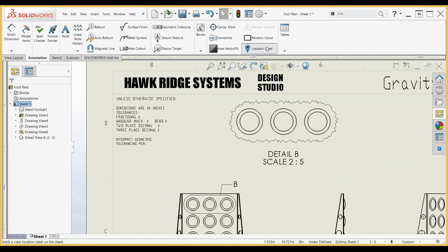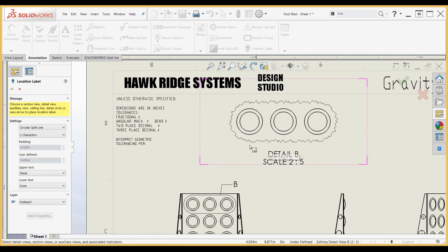If that purple box appears, that means that I'm going to drop the note inside the view and it will be linked with the view. But let's say you have a lot of views close together and you want to lock it inside of one view specifically. If you double click on a view, you can see that purple box gets thrown there kind of permanently.